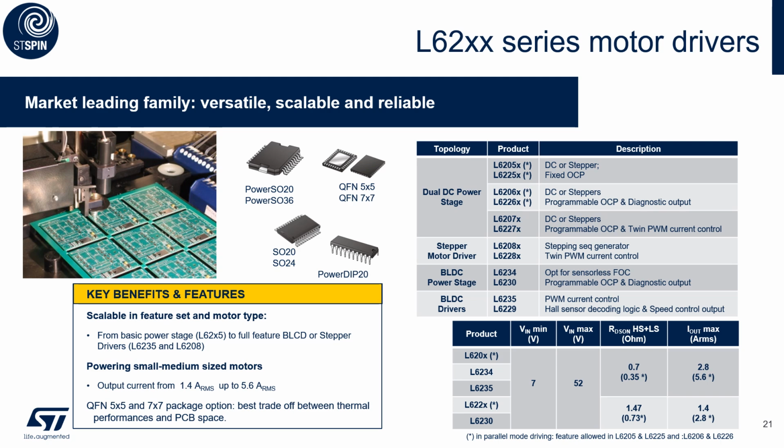If we want to go higher in terms of power, you could go with our best-selling motor driver family, the L62XX family. The L62XX family is a DMOS fully integrated motor driver with a non-dissipative overcurrent protection of all the high-side power MOSFETs and a thermal shutdown, realized in the BCD multi-power technology, which combines an isolated DMOS power transistor with CMOS and a bipolar circuit on the same chip.